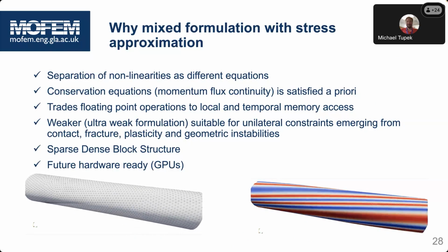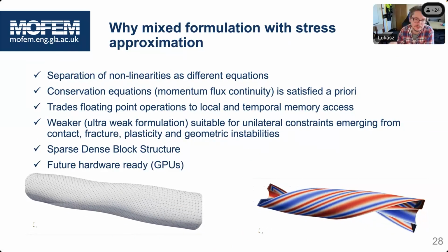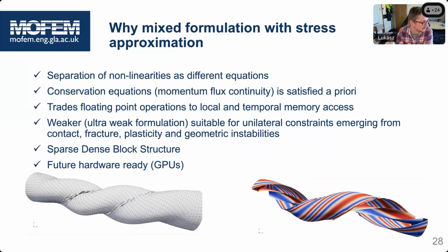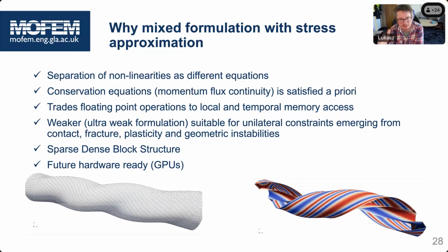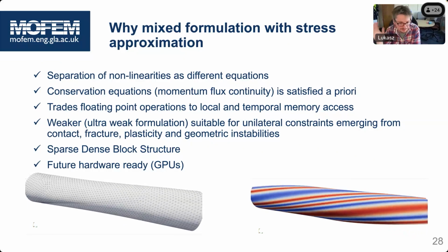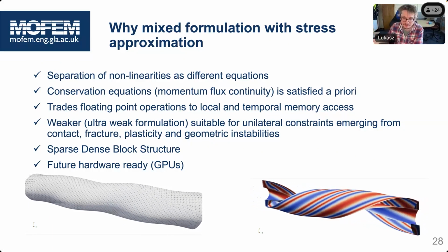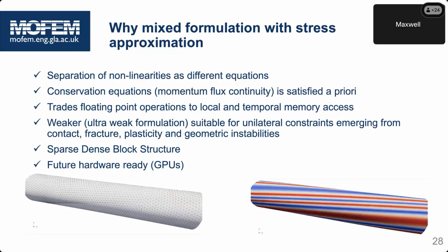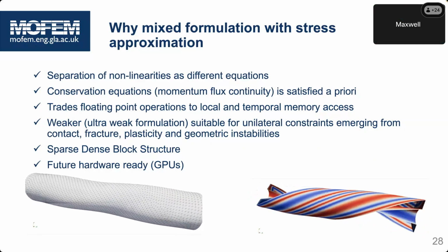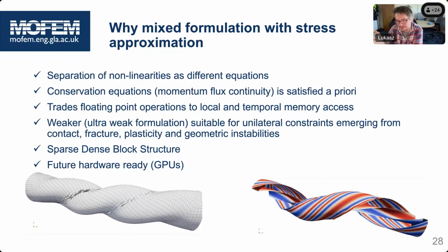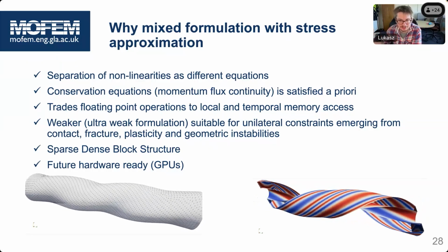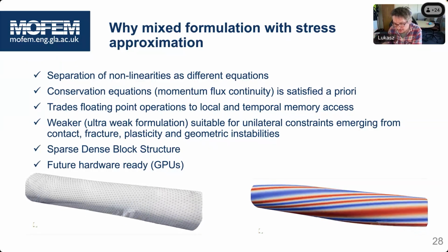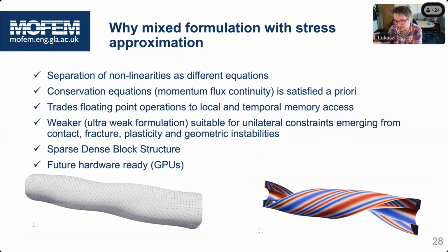So thinking about that, if you have, for example, a thermal problem, and you want to have radiation on the boundary for the mixed formulation, you can add this hybridized field for the temperature on the boundary. Or when you have elasticity and you have springs on the boundary, you can add the displacements on the boundary.